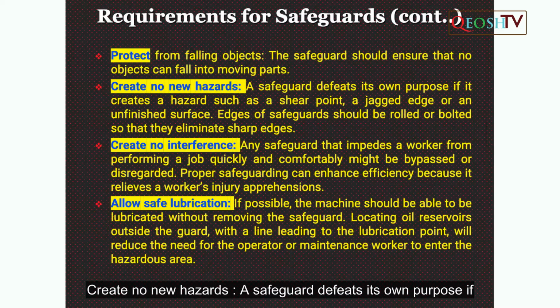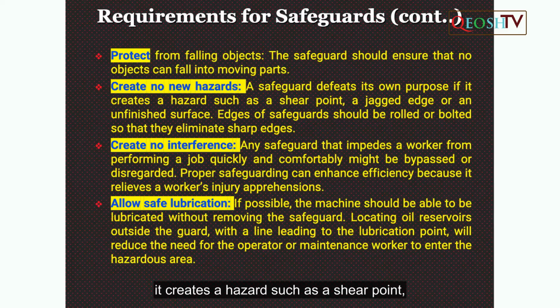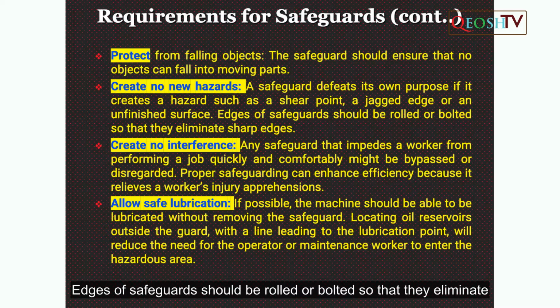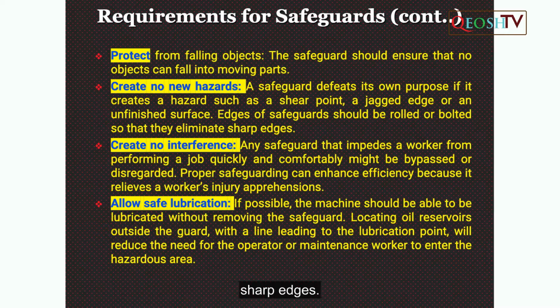Create no new hazards. A safeguard defeats its own purpose if it creates a hazard such as a shear point, a jagged edge or an unfinished surface. Edges of safeguards should be rolled or bolted so that they eliminate sharp edges.